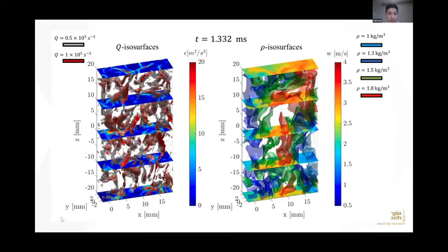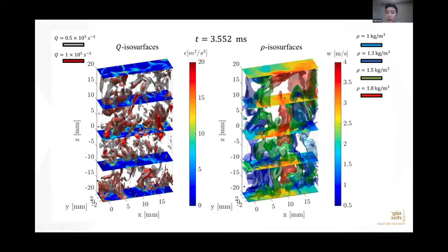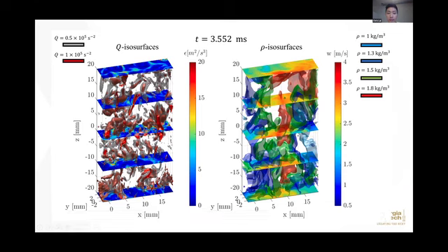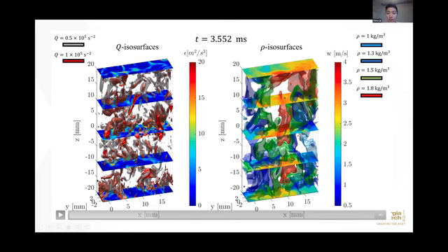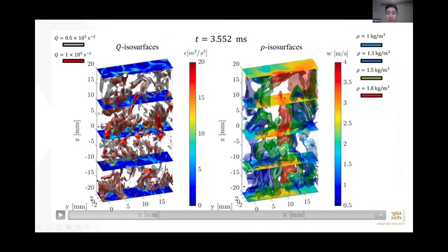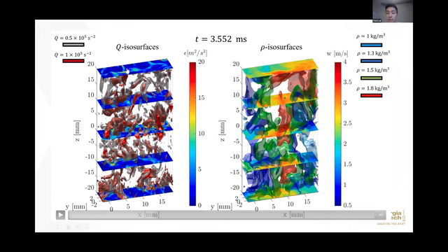What I want to emphasize is in the left-hand figure, the red tube-like structures are the turbulence, the swirling motion, and the blue cut planes show you the highly dissipative region. Only by solving the Navier-Stokes equations with a full velocity vector could you retain the thin structure of this highly dissipative region. This is a known feature of turbulence: the highly dissipative regions are thin sheets.